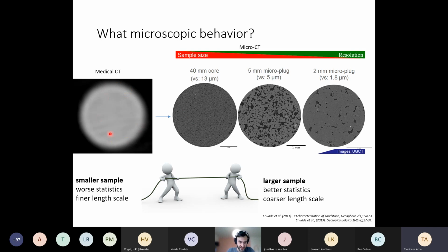And you can see here that because the medical CT has less magnification, it has a wider point spread function, and thus it is blurring out more, making the resolution lower, because now you can no longer make out the individual pores, the individual peaks in your signal, while you can do that to some extent in this example.